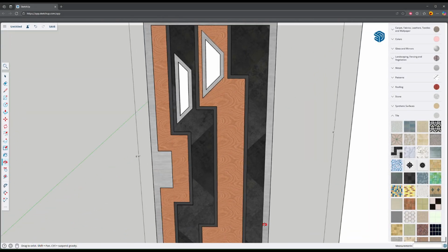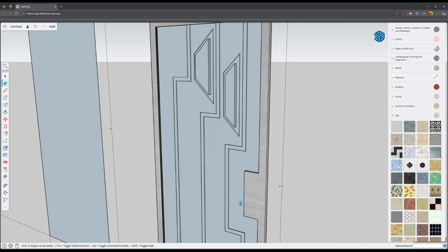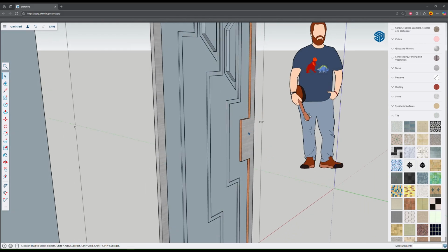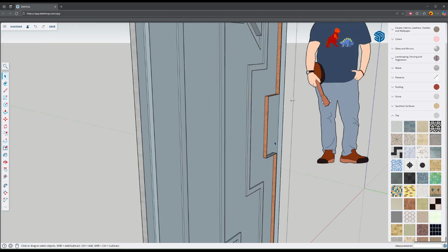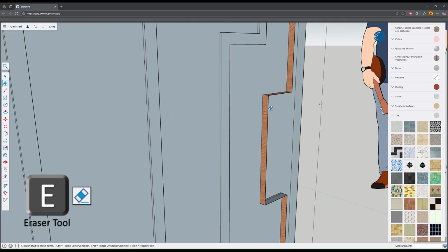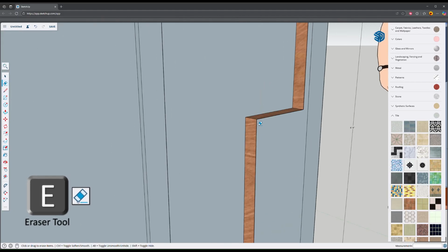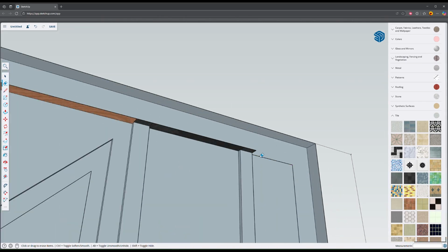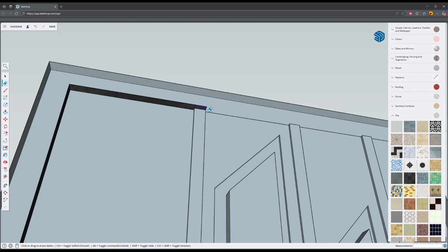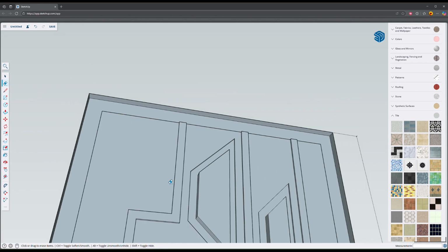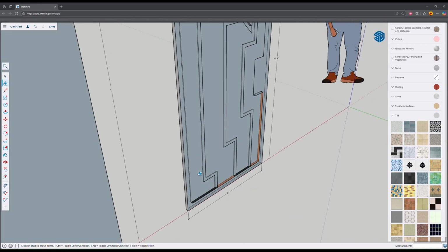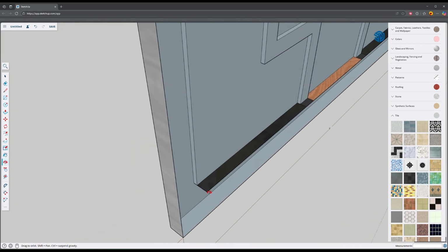It's time to clean up the geometry on the back of our door half. I've gotten into the habit of deleting any geometry that is unnecessary to the model, in the hopes of decluttering and hopefully improving the render. Be careful what you delete. Some of this geometry is the backside of front-facing geometry that is necessary. When deleting, I often do extra orbiting to ensure that there is nothing important behind what I am erasing. Notice that I leave the outer side geometry, as this will serve as 1/2 the outer edge of our door.